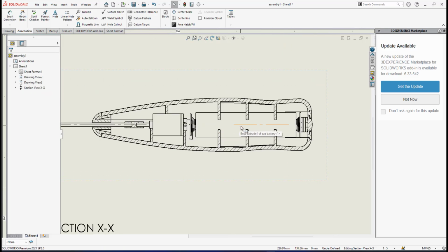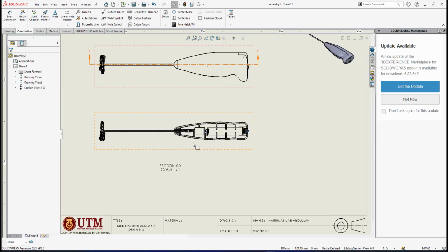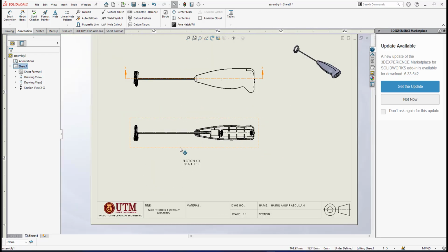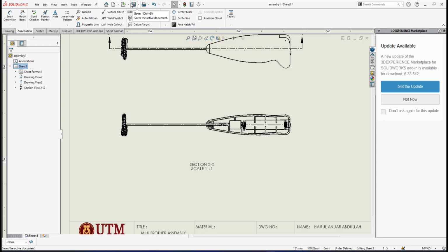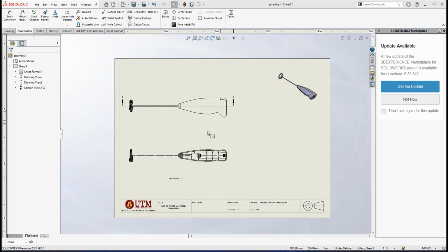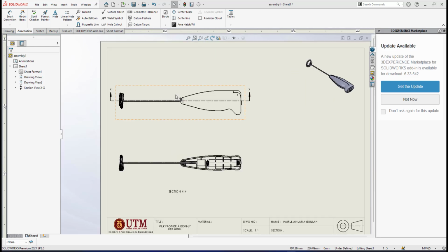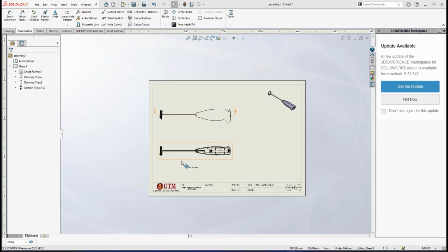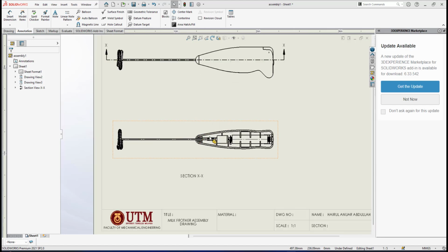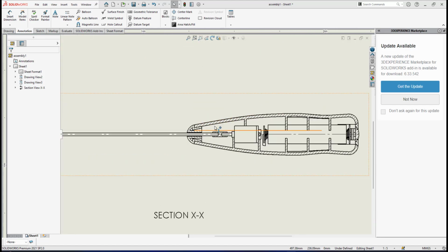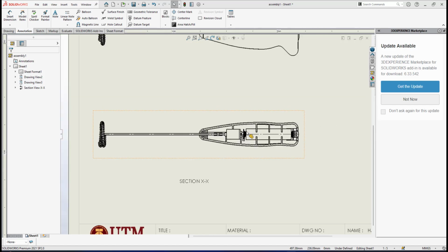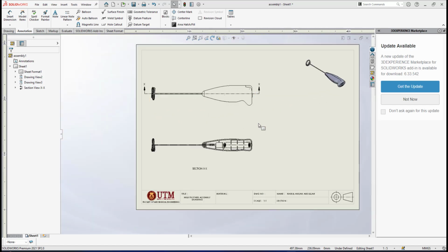Okay, for this line, I can adjust it. Put it like this, to show that it is cylindrical. Okay, better to have one for the center line. Okay, I save my file. Alright, the next thing to do is that since I've completed this top view with the section line, and this front view is a section view with the hatching lines for all the components. Alright, the next thing to do is about bill of material and also the balloons.